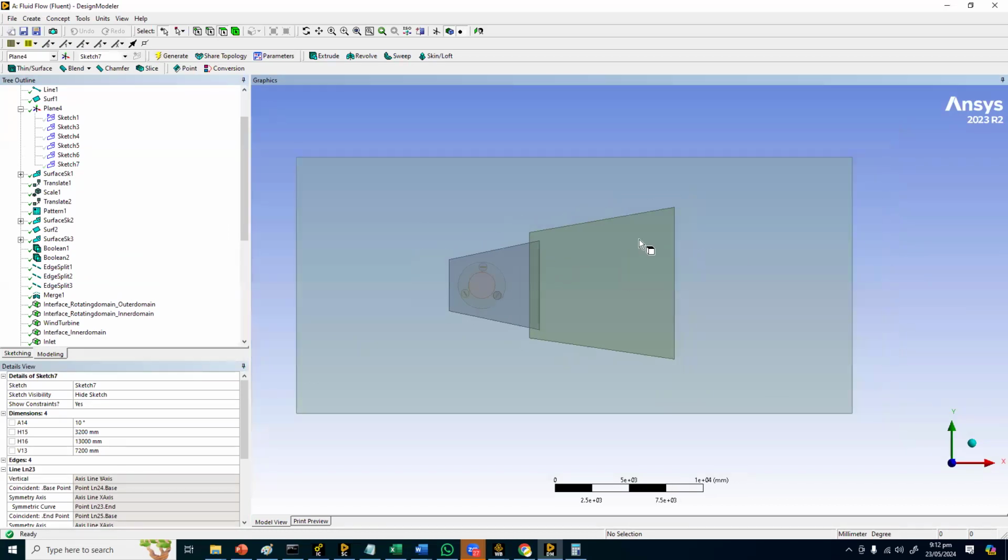So now this region can be, depending on the solution, you can extend up to outlet. Sometimes people do that thing. For example, sometimes what they do is that they extend all the way around the outside of your domain, and that's not a problem. This will only refine the mesh where this domain is. Outside the domain, we don't have anything, so it will not define the mesh outside. It will only define the maximum mesh inside the domain. So what people can do here is that they can extend it outside.